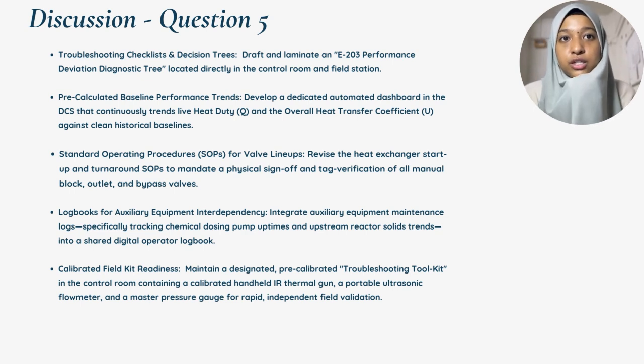Maintain a designated, pre-calibrated troubleshooting toolkit in the control room containing a calibrated handheld IR thermal gun, a portable ultrasonic thermometer, and a master pressure gauge for rapid independent field validation.